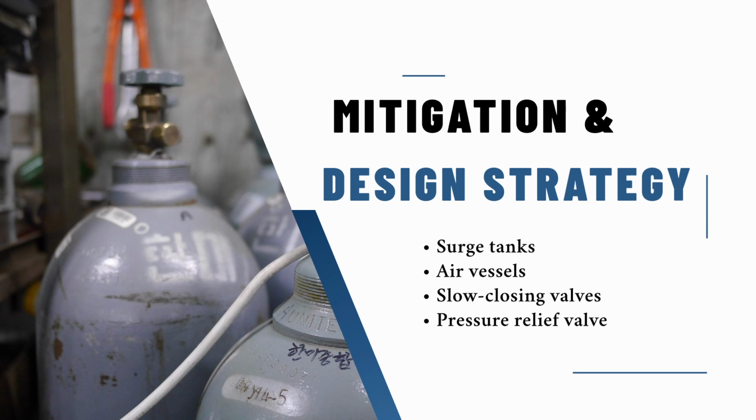Just like the example I gave of how we mitigate this problem by selecting the right pipe pressure rating, we can also do the same on other components. Instead of using pipes alone, we can adopt surge tanks, air vessels, slow closing valves like we looked at, or pressure relief valves.